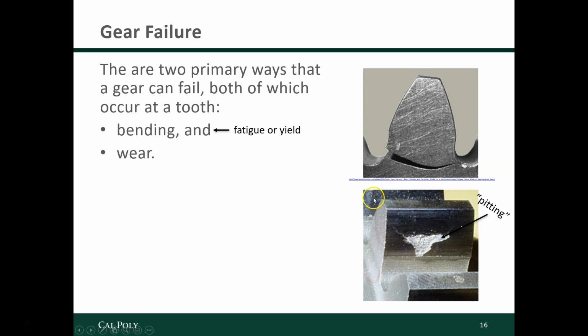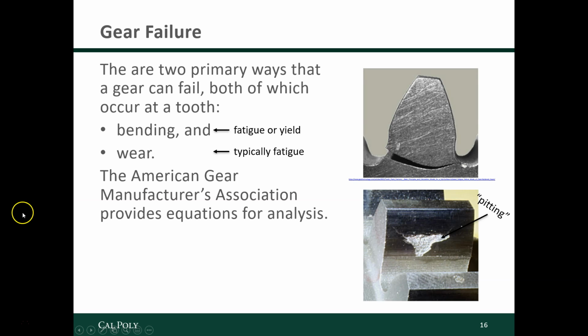And so that's not going to result in a very good engagement. There's going to be higher stresses in the surrounding area. It's going to be noisy. It can end up with little bits of debris inside your gears that can cause other ones to wear. So overall, not a good situation, one that you want to avoid. That typically occurs because of fatigue. It's unusual for pitting or some sort of wear to occur because you've exceeded the stress just once. It's typically over lots of repeated cycles that this sort of thing can happen.